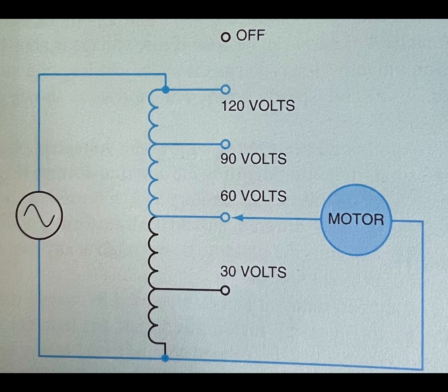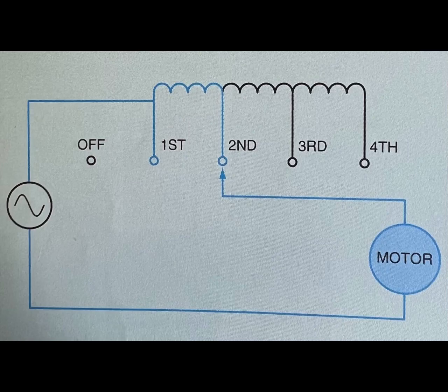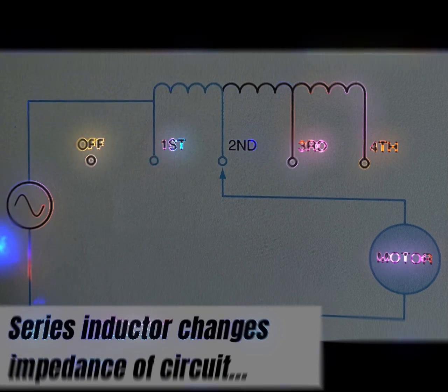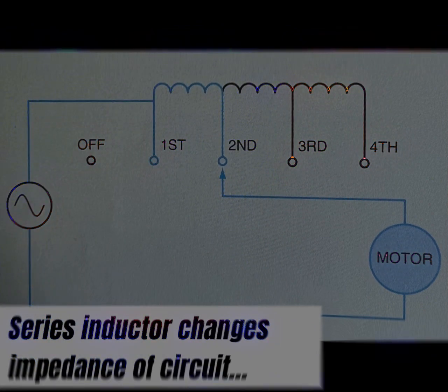There are several methods used to control the voltage supplied to the motor. One method is to use a triac with a phase shift network similar to the circuit. When triac circuits are used with inductive loads, care must be taken to ensure that both halves of the AC waveform are conducted. Only triac controllers intended to be used with inductive loads should be used for motor control.